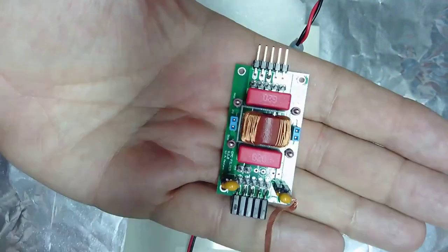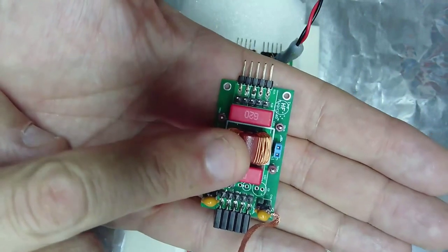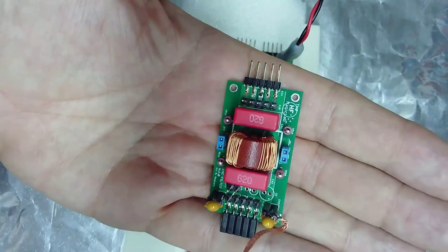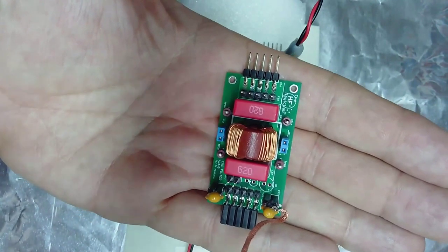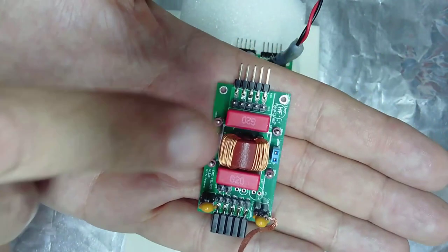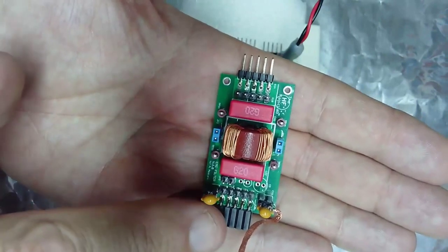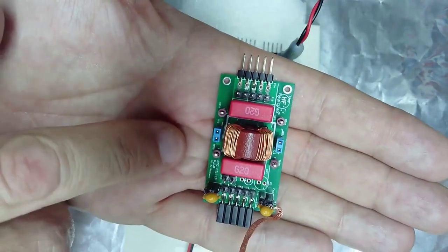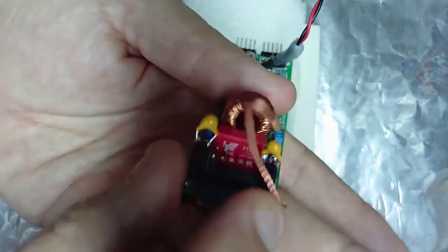basic demonstration. I have 2 capacitors. I have 1 common mode choke and 2 Y capacitors. I know that in this application, we don't usually say X and Y capacitors because there are no safety rules like with the mains, but in this way, everyone understands. These X capacitors go from positive to negative, and Y capacitors go from positive to chassis and from negative to chassis. Additionally, I have a common mode choke, but this common mode choke is being short-circuited.